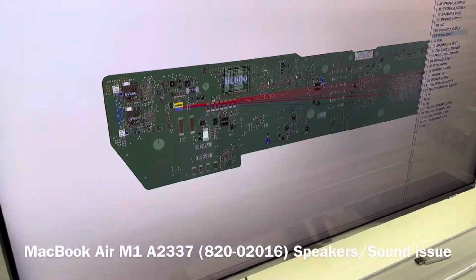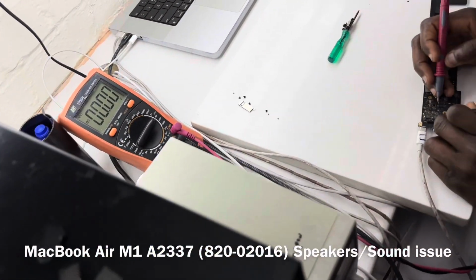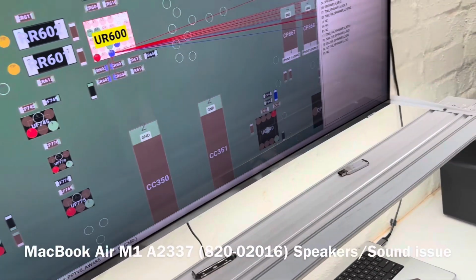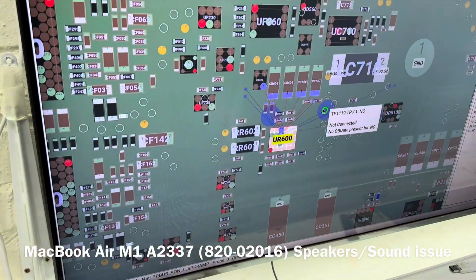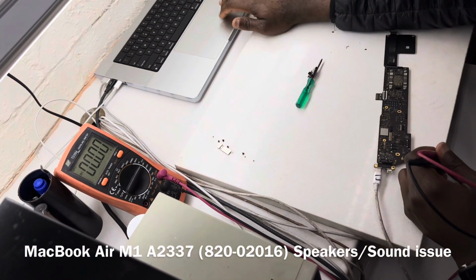1.8 volt is definitely present. Let's just confirm that, but we know that it is definitely present. 1.8, it is present. Speaker reset, we have measured that. PP bus, that we also believe should be present. Let's measure that. And yes, it is present.